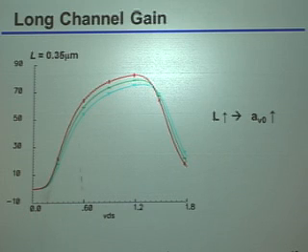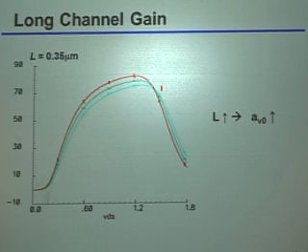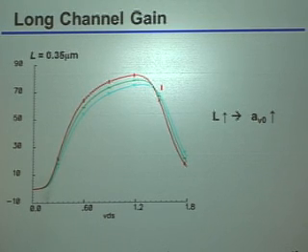So this would be, for example, another plot that, again, is just showing that over the same voltage swing range, indeed, potentially you could get a higher intrinsic gain out of the device. And once again, the whole trick here is that you're just going to choose whatever the shortest device is that actually meets your specification. Now, having said that, just before we move on, can anybody else think of another way of actually getting more gain out of a device rather than just increasing the channel length?